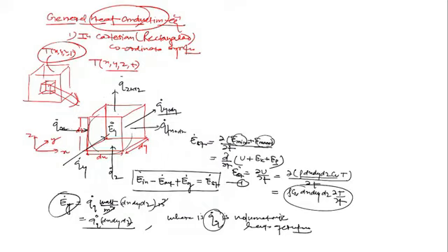Basically Cv and Cp are equal, that's why I can also write Cp as well, no issue, since Cp is equal to Cv for incompressible substances. Then I can also write rho Cp dx dy dz into del T upon del t. Why are these going outside? Because they are not going to vary with time. Any problem beta? So we have defined the generation and storage terms.